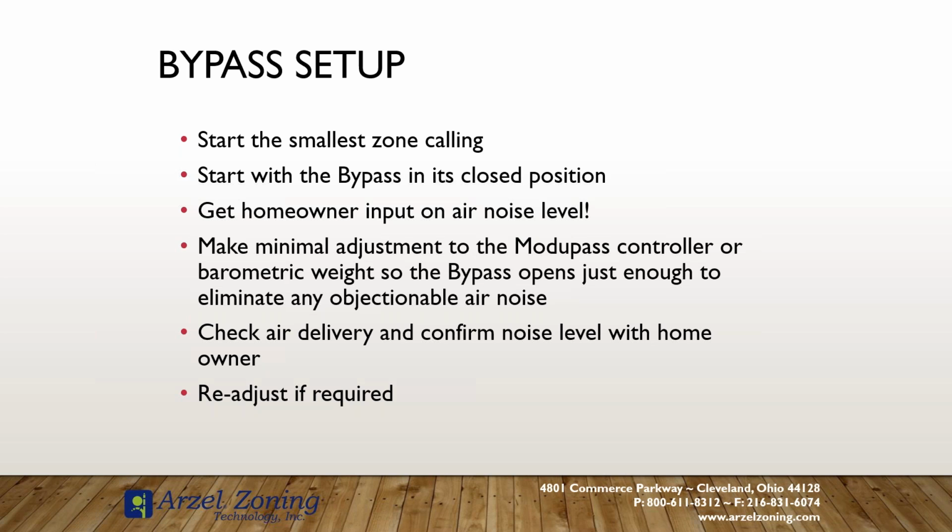You'll probably find more often than not that bypass isn't required. So it's a good thing to measure your static pressure, get your customer's perception before installing the bypass duct. And then if your pressures say you need it, and if your customer's perception of airflow noise says you need it, you price it into the job, you have it available, go ahead and install it. But if your customer's satisfied with it, you don't have to put the bypass in. If your numbers say you're good, you don't have to put the bypass in. And now you can just return that to your distributor or stock it for the next job. And that's profit on the job.